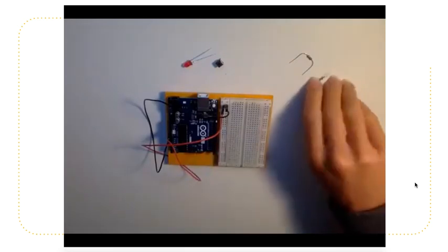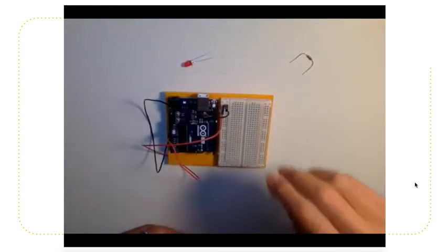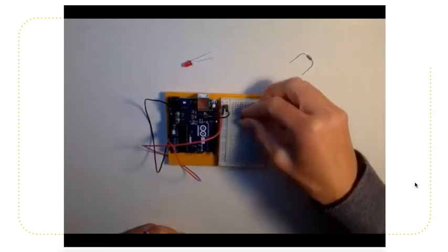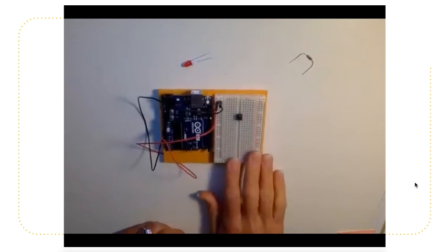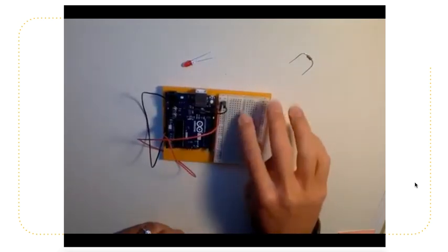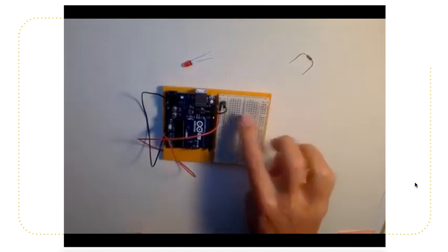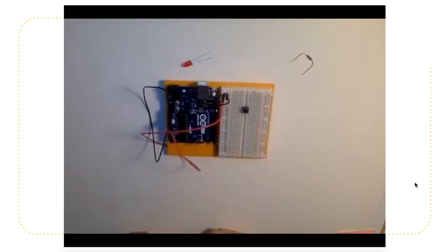So once you get that situated, I'm then going to start with my switch. That's just the order in which I decide to build it. Usually when you're using a breadboard, you want to put the switch across the middle channel, just so you don't get any interfering connections with any other positions on the board. Right now, there's nothing connected to this push button switch, so there's no direct correlation between those two points there.